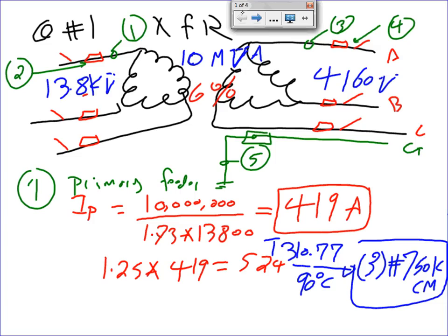So if you go and measure the voltage between the ground and phase A, you wouldn't see anything. You can literally grab phase A and tie it directly to the ground and nothing will happen. No short circuit, nothing. That's the beauty of a delta, ungrounded system, guys. They use it in assembly lines and transmission lines because you can get the first hit and you're not down. You can handle the first short circuit on one phase.